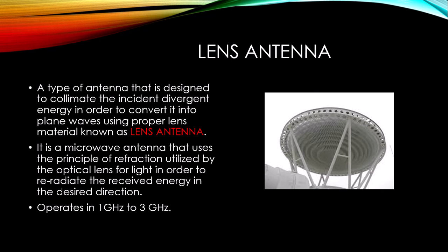A lens antenna is regarded as a radiator which operates on the collimating action of an optical lens. Its operation is similar to reflector antennas. A reflector antenna allows the energy falling on its surface to collimate in the desired direction, converting spherical waves into plane waves. This causes an increase in the directive gain offered by the antenna arrangement.